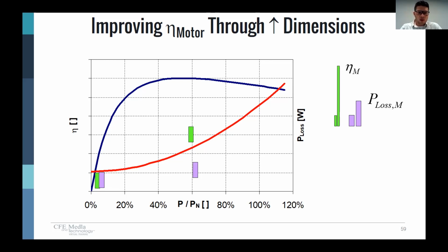So what we can do is take, let's say, a motor that's rated for 5 horsepower, and that would be 100% load in our rating. It has an efficiency of, let's look at this curve here and say about 85% is a good number for a regular standard efficiency motor of that size. If we were to underload that motor, if it was rated for 5 horsepower at 100%, what if we lowered it to about 60 or 70%? What happens to the efficiency?